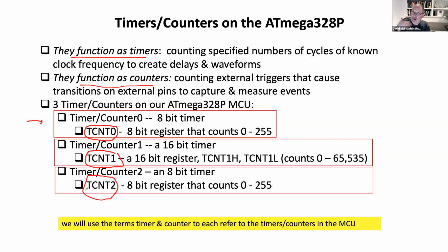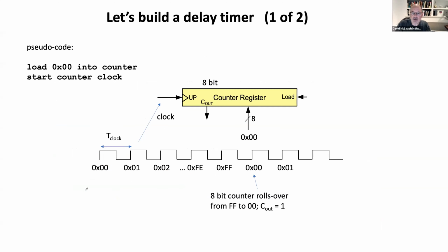And by using the timer to do it, instead of having to do it all ourselves in a loop, you can use the CPU to go off and do something else. So you configure the timer, you tell it, go do this, and you take care of this. Meanwhile, we're going to be using the processing power to go do something else because we've delegated to this timer peripheral to go off and do the counting.